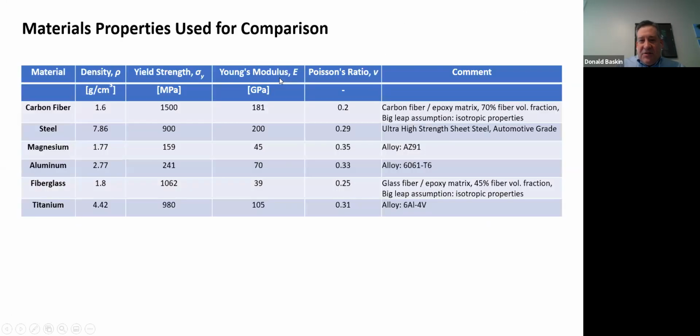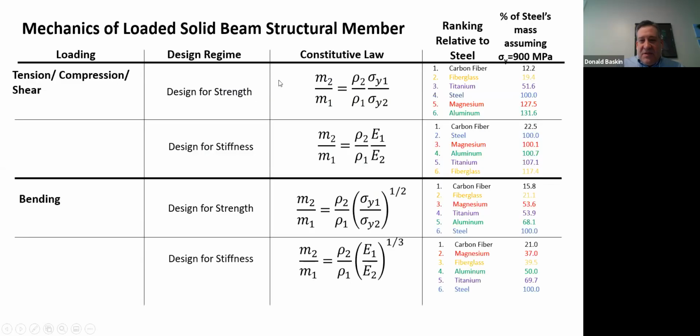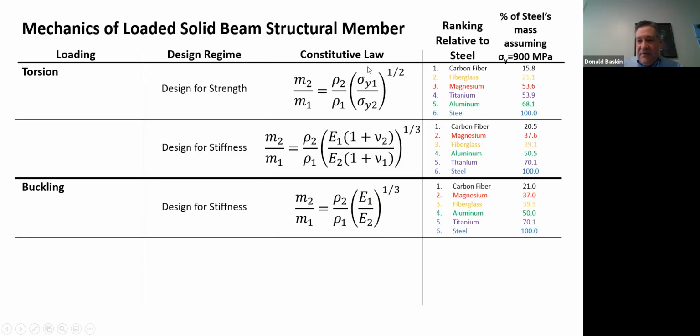I have the Excel sheet that produces this somewhere. And if you were curious, Steve, you could go and start plugging in different values. You could look up 3-2.5 titanium, commercially pure titanium, 6-4 titanium, and you'll see that the strength changes. The stiffness doesn't change, or changes a tiny, tiny little bit, but the strength changes, and then you can start figuring out which of these materials make sense.